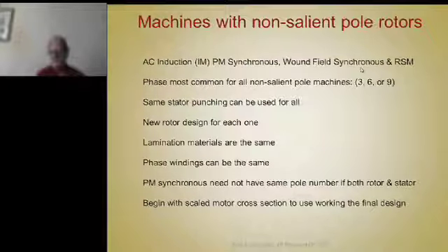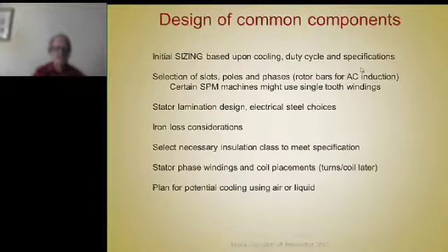And he would start with, we'll talk about sizing, but going through that sizing process, he would draw a sketch of the machine, and with lots of years of experience, you can begin to pick diameters of rotor given the stator. You could pick tooth widths and yoke thicknesses and magnet thicknesses and things like that, just based on your experience. But to use that experience, you have to use a scaled layout or a scaled drawing to do it with. So that's very useful for machine design.